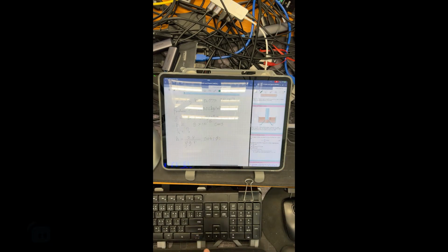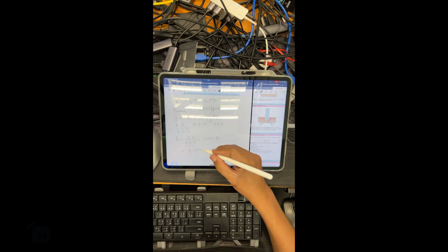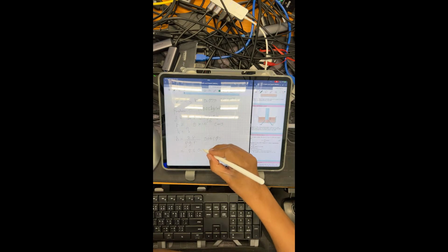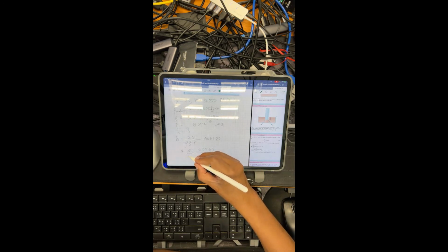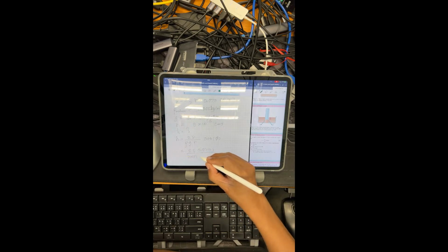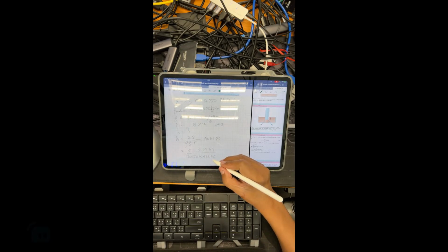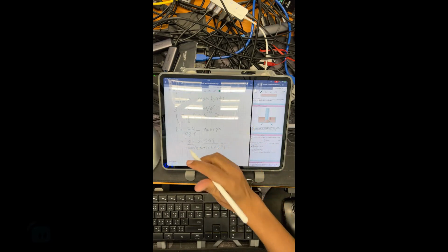Here, 2 times gamma, which is very tiny, only 0.073, divided by rho, which is 1,000, 9.8 for the acceleration on Earth, and the radius, which is very tiny, 5 times 10 to the negative 5. That's the thing we have to compute.